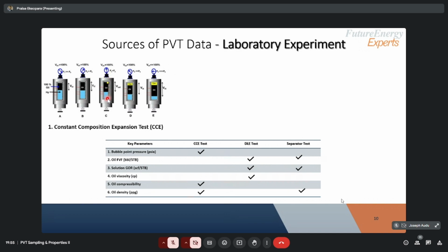Now, that 12 we are hitting is the saturation point, and we define saturation point or saturation pressure as the highest pressure at which the first bubble of gas can be seen, can escape the oil phase, the single phase, right? So it's roughly 100%, and this roughly means that there are some traces of gas that must have appeared, right?